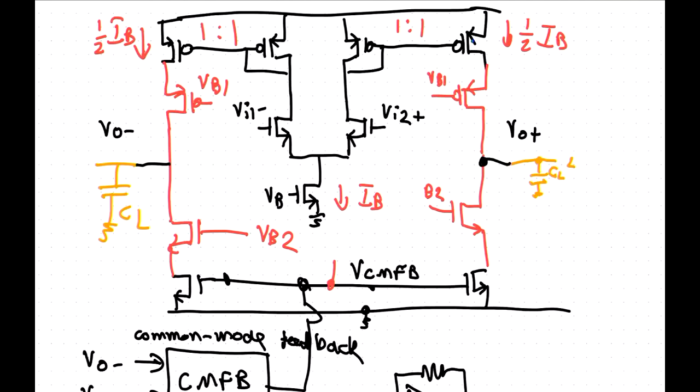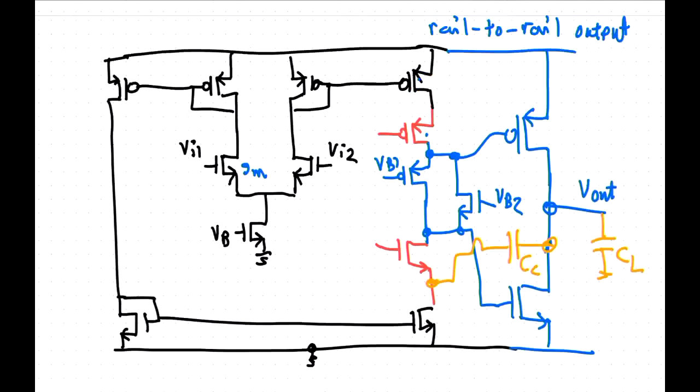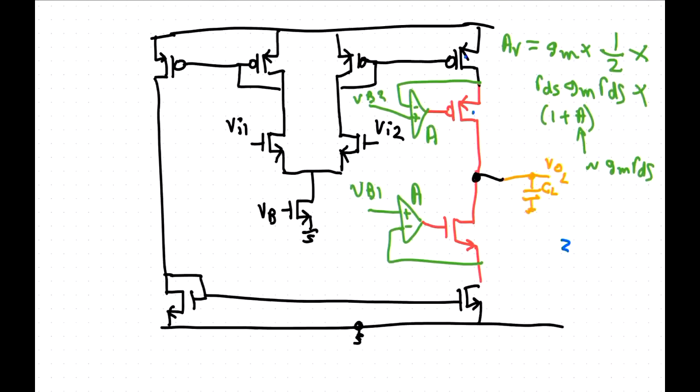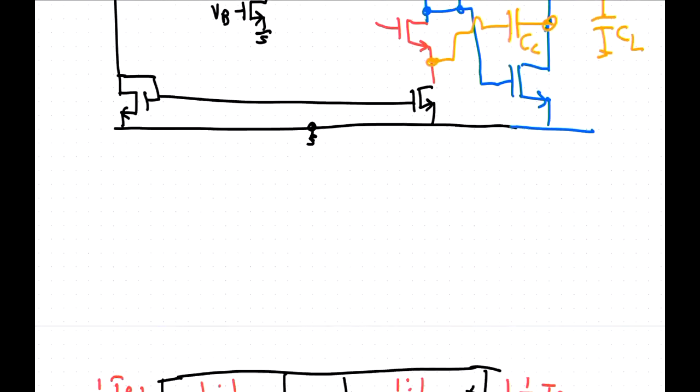We looked at fully differential, which is essentially just taking the current mirror op-amp, having all the cascodes in that you should have, and getting rid of this Y here, so you have two outputs. Now when you do that, you need to introduce a common mode feedback system.